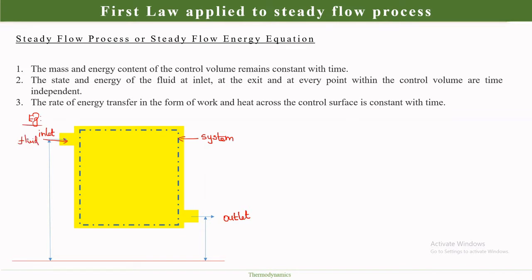Some fluid is getting in, and I know some properties of the fluid: my pressure P1, the specific volume Vs1, the area A1, the internal energy U1, and my velocity V1. Don't confuse this specific volume, which I will write as Vs, with velocity.